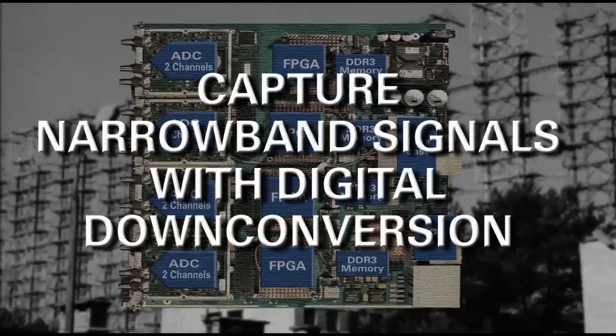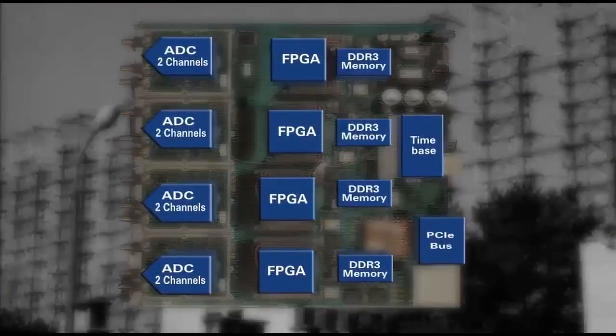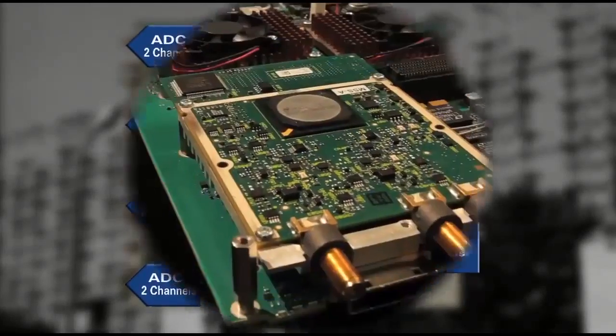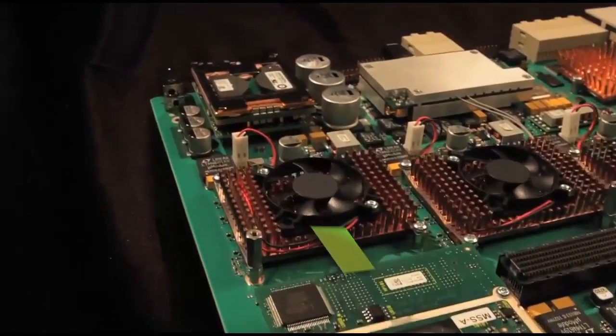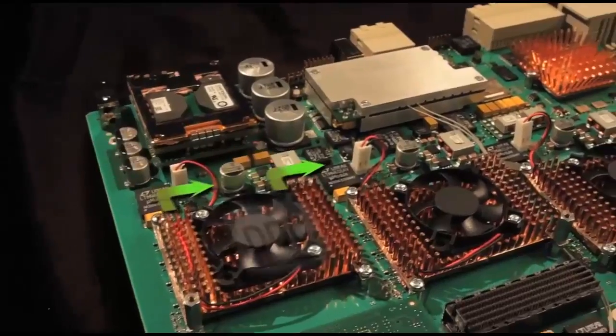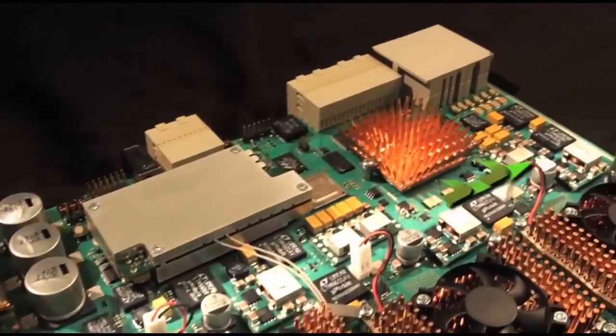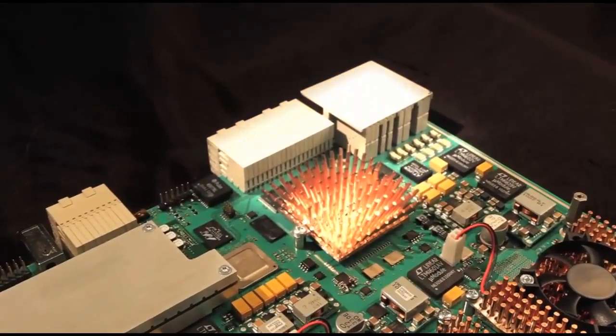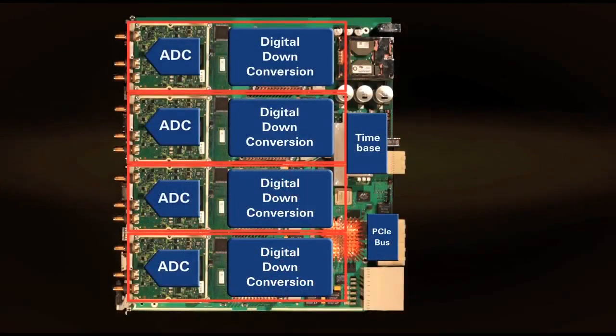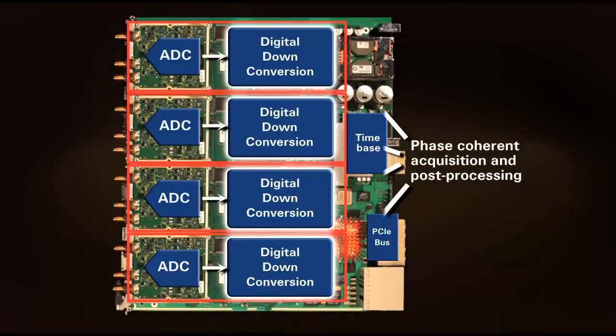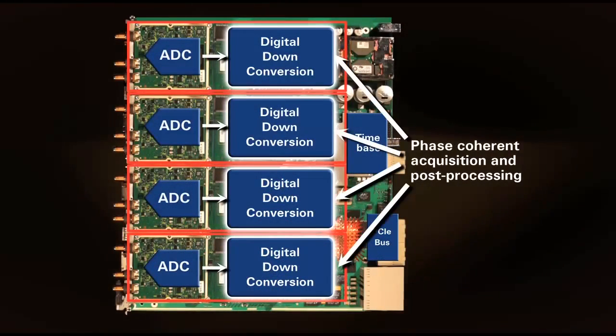When using a wideband digitizer to capture narrowband signals, the embedded digital down conversion capabilities help achieve greater sensitivity and better measurement resolution, and help you tune and zoom on your narrow spectrum content of analysis. The digital down converter's implementation allows phase-coherent post-processing across multiple channels.